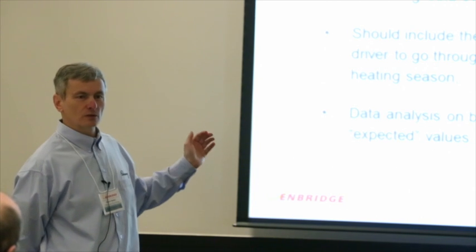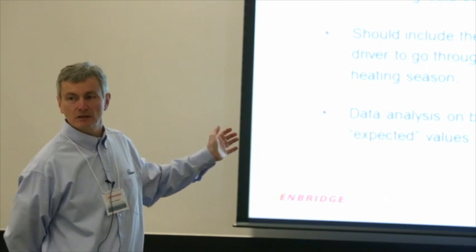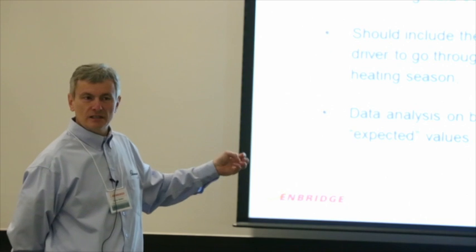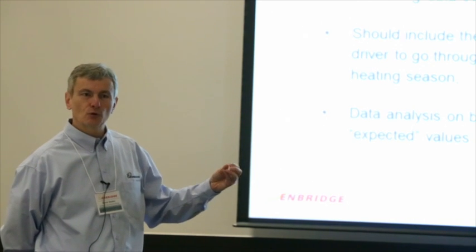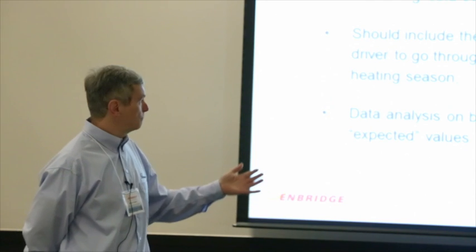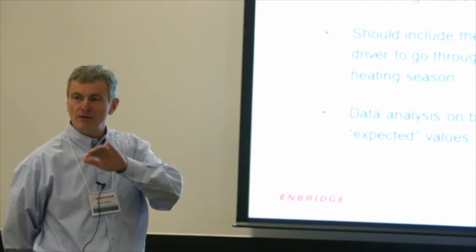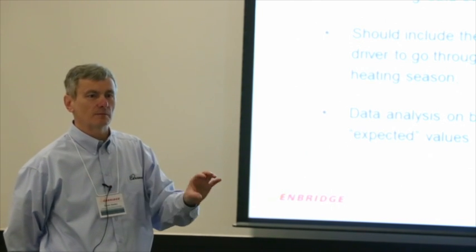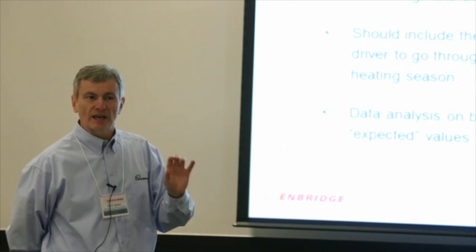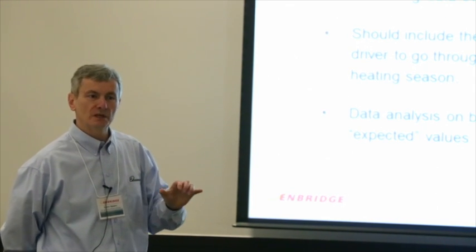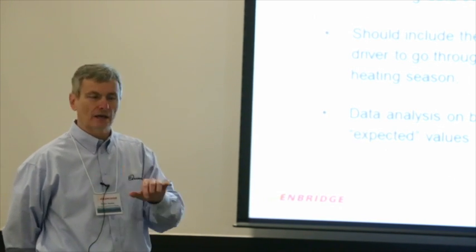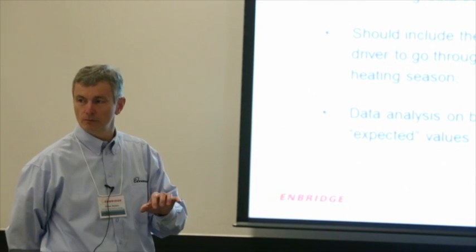But let's say you're trying to find out some seasonal averages. Well, then your energy driver is seasonal, it's temperature. So you have to go through the whole entire range of one season to be able to justify what the seasonal impact is. I can't tell you what the baseline period should be because it depends on each energy driver separately. But you have to let it go through the entire range for it to be meaningful.